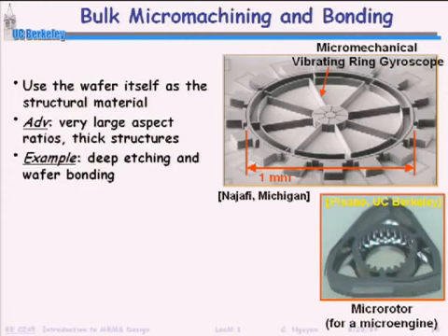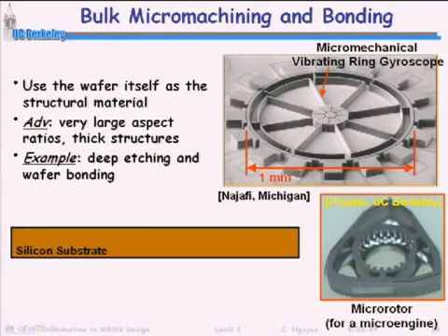How was this made? This was made using planar processing. You start with a silicon substrate. You use a technology called deep reactive ion etching, which is a technology used to do this through-wafer etching that was really developed for MEMS, to etch very deep into the silicon substrate, with very straight sidewalls. We will talk about exactly how this works in this class.